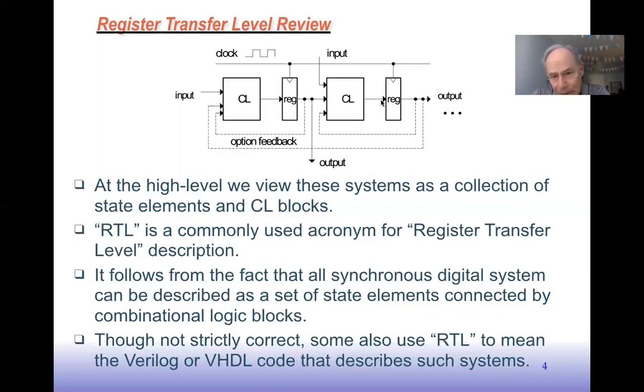In going from register to register, we move through the combinational logic block, and that's where the real computation happens, or at least the operations. So this leads us to think about this as a register transfer level description of our circuits. It abstracts away a lot of the details, and that's nice. It helps us think about the movement of data through the system.